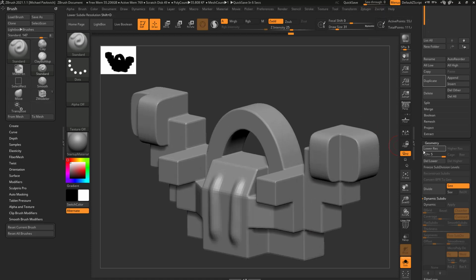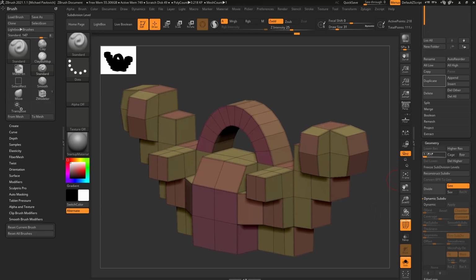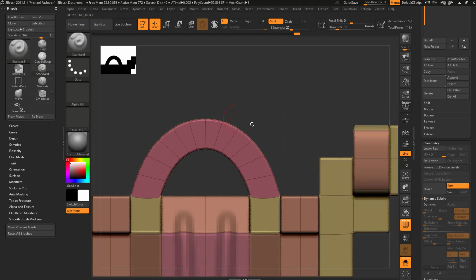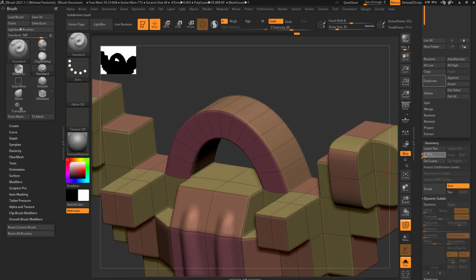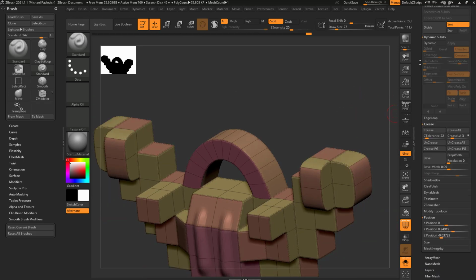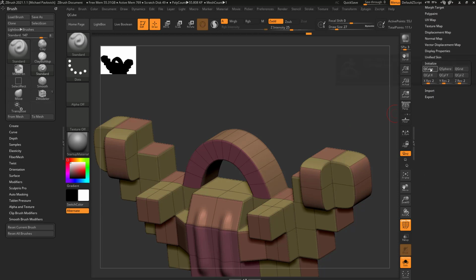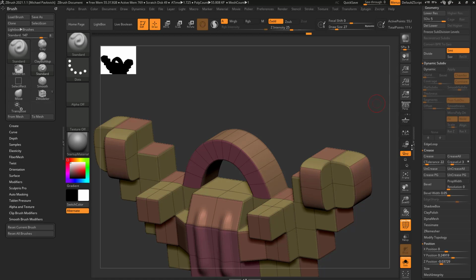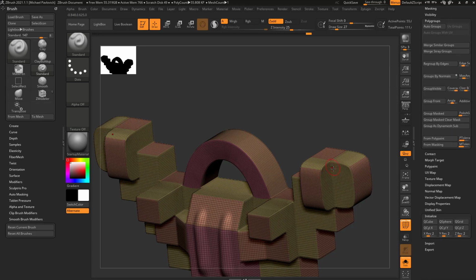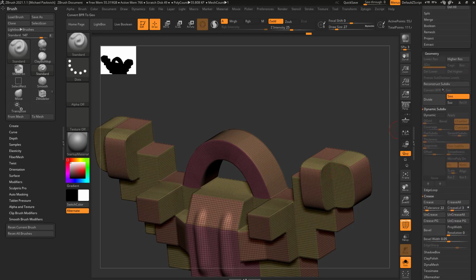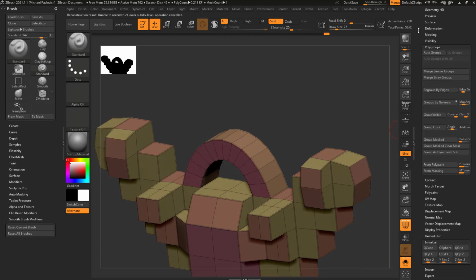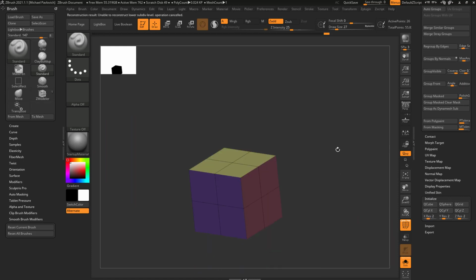Now when I have my subdivision here, if it goes down to subdivision level 1, this is the geometry, and then smooth subdiv is essentially just hitting Control D, and all your polygons here will be nice and equally subdivided. I'll have perfect subdivision history all the way through. However, if I go back here, let's go ahead and just take our mesh here, and we'll just say, give me another initialized Q cube. Oops. It's going to say if it has subdivision levels you can't convert it, just hit delete lower. And then that'll get rid of our subdivision levels. This will keep this geometry. And if you ever want to, you can hit this reconstruct subdiv and you can get your subdivision history back if you want.